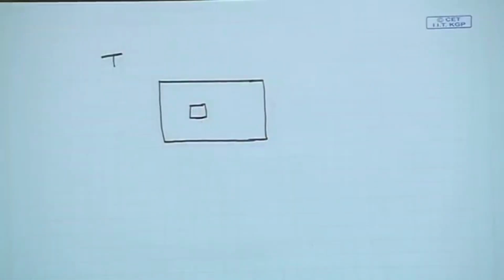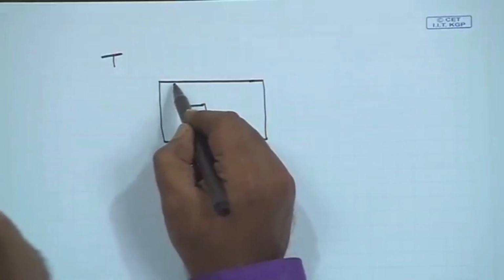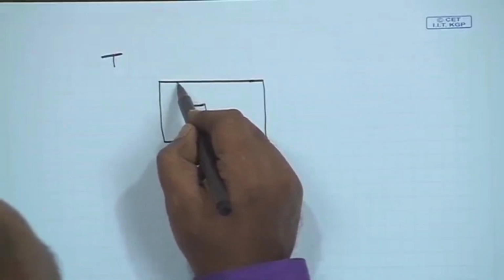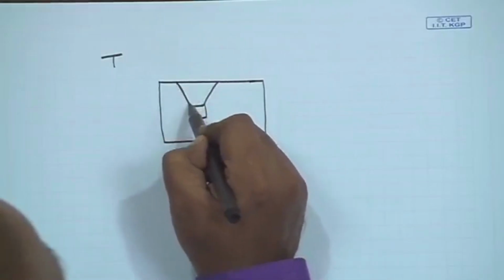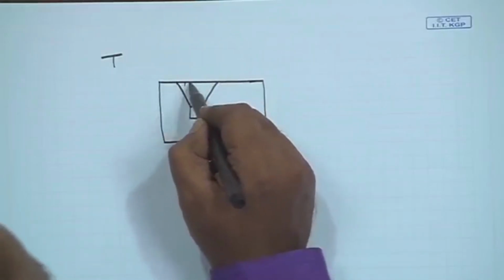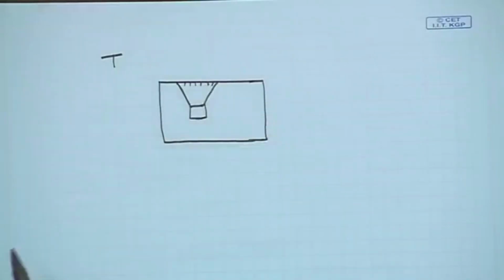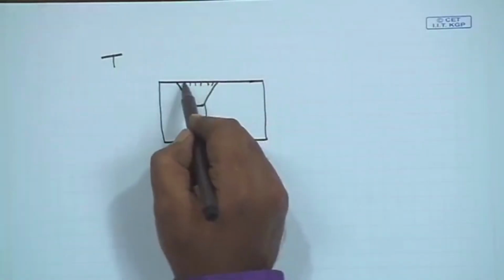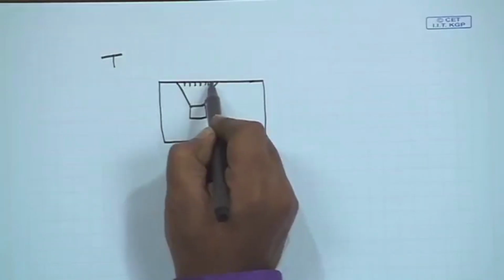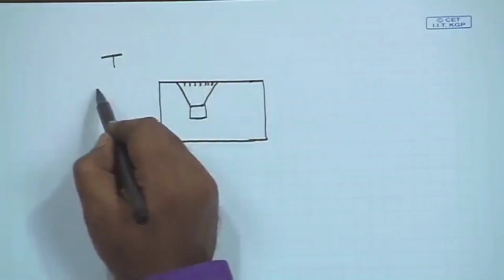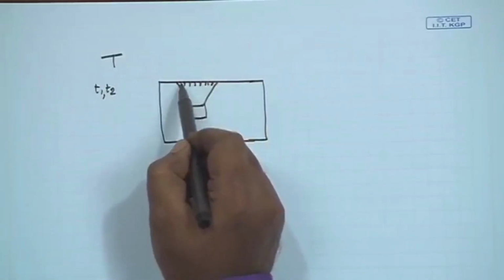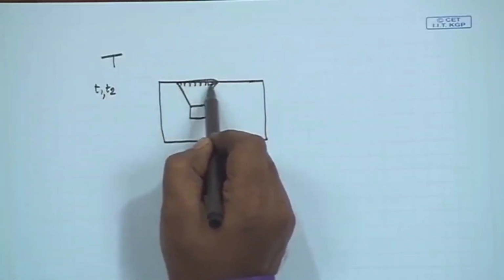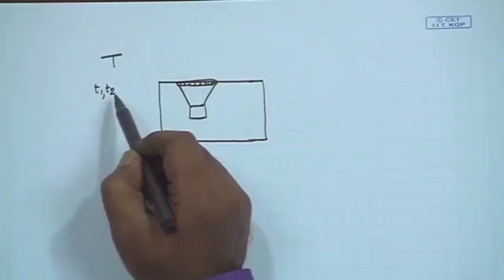We figure out the cone of influence, the primary input cone on which this block depends. Naturally, if we can reduce the transitions occurring in this block between two successive patterns T1 and T2 that we apply to the circuit, if we find that for this part of the input the transitions are fewer,